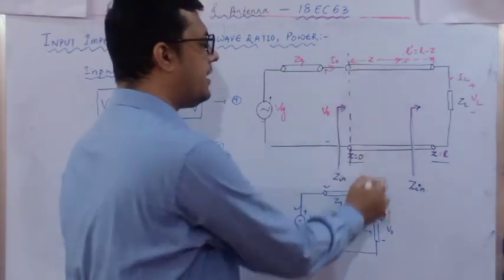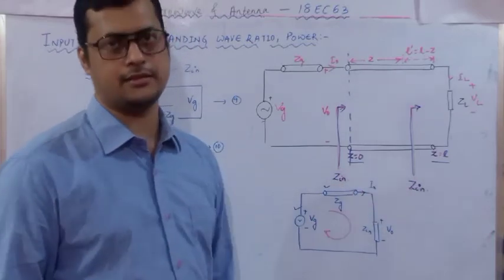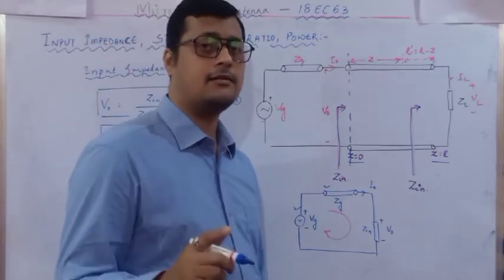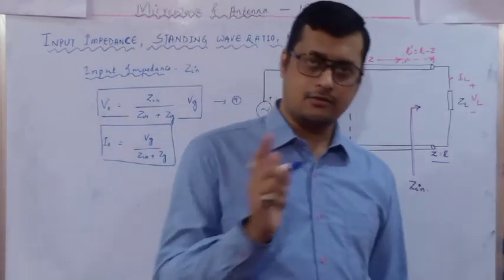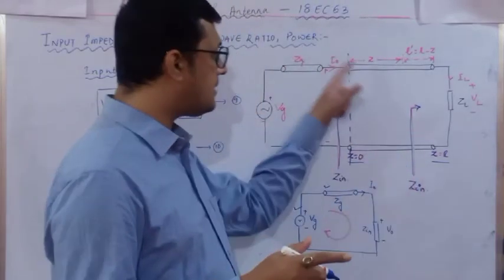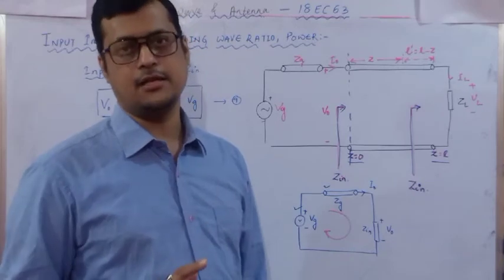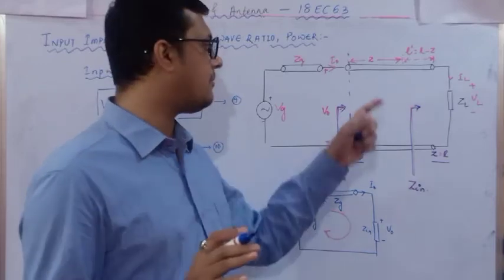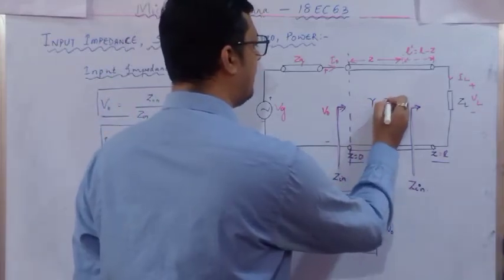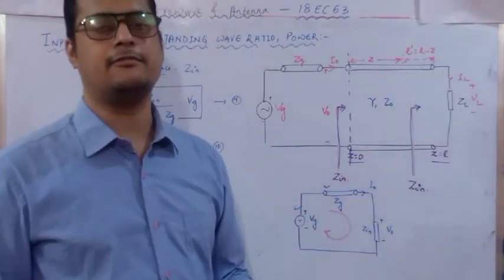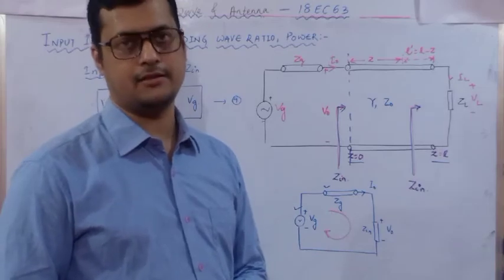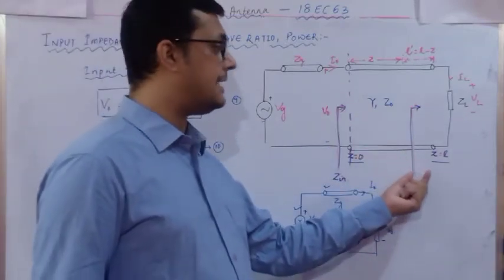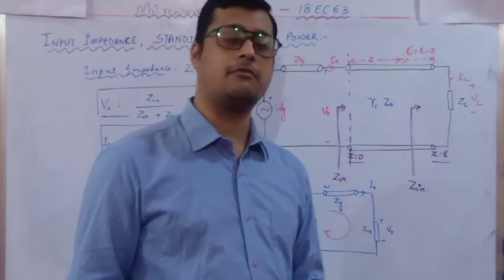So here you can identify L1, L2, L3, L4, different positions. With a different number of positions, your impedance is going to change. But one thing which remains constant is your propagation constant throughout the system, and the characteristic impedance of this line will also remain constant throughout the system, because your RLGC parameters are not going to change. So your characteristic impedance and propagation constant, meaning Z0 and gamma, will not change with respect to the position. It is independent of the position. Now with the help of these two, we will proceed to determine, at z equals L, what is our potential and what is our current.